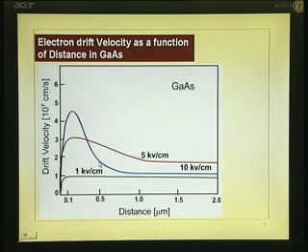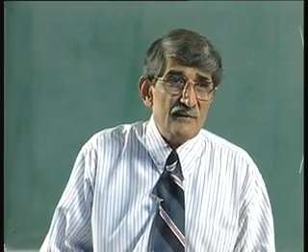So, you can see now if the channel length is less than 0.5 micron, the transient phase is not over. As a result, throughout the channel the velocities will be much higher than 10 to the power 7. So, the time required for transit will be very small, because the average velocity is high, and because of that you will get higher gm. This is where the benefit of gallium arsenide is present.